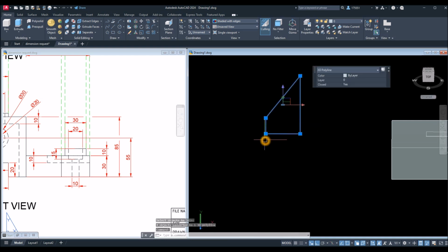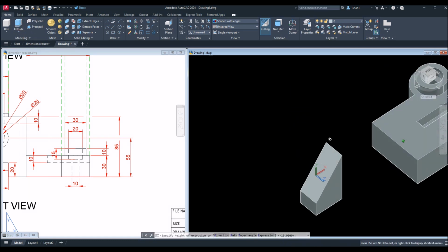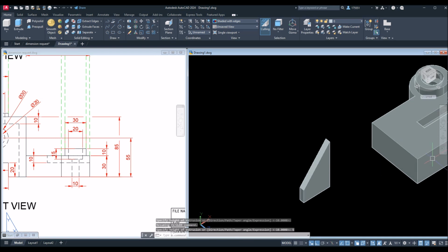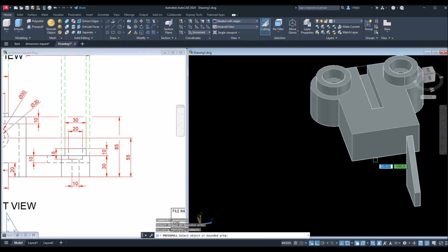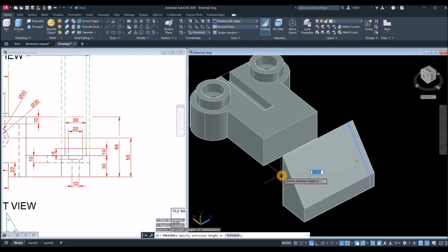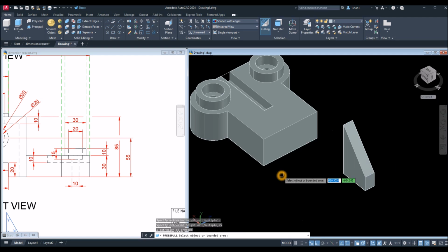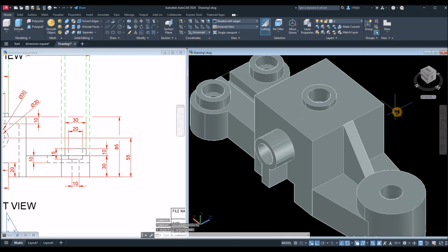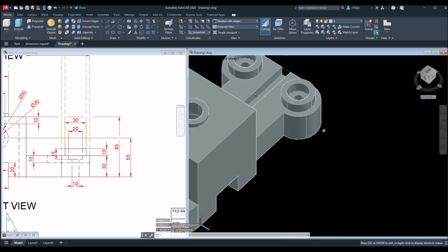Now I could extrude this one for 5 units going to that direction. So 5. And then use press pull command because I want it centered. So it's only 5. I use only 5 units to extrude. And then for this side, hover over, extrude it to the opposite side for 5 units. So the total extrusion is 10. Now I'm going to bring back my hidden objects. So end object isolation. Now it's centered.